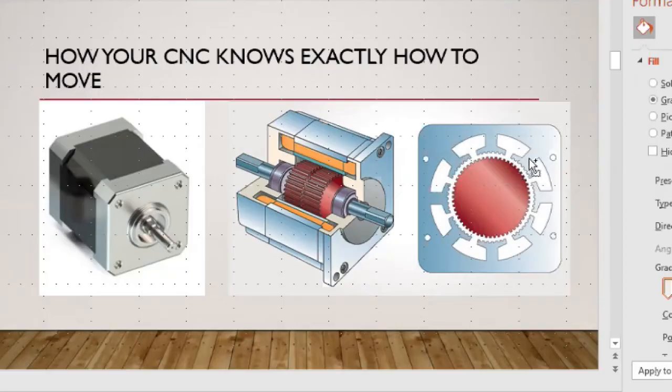And then this one would be turned off and the next one would turn on as far as being magnetized, and that would pull the armature a little further. And so it depends on the number of magnets that are in the armature. That would depend on what they call the resolution, or how refined that step is. That's why they call it a stepper motor.